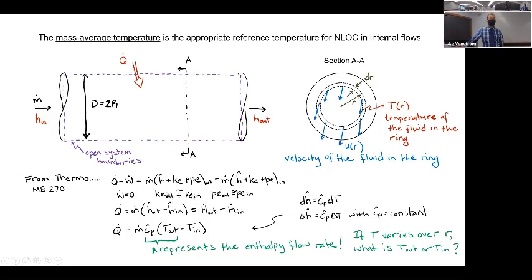Those were the V squared over 2 and the g z, yeah? But there is no potential energy change, right? It's a horizontal tube in this case. And there is no significant change in the velocity, right? So there's no change in the kinetic energy of the fluid. It still has the same velocity, right? It does have a lower pressure, right? Because it's the pressure potential that's used for overcoming the friction, not the kinetic energy.